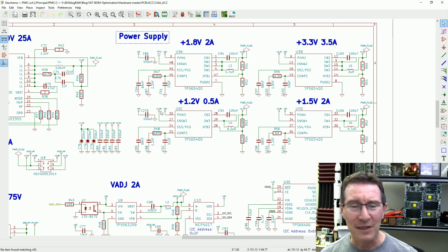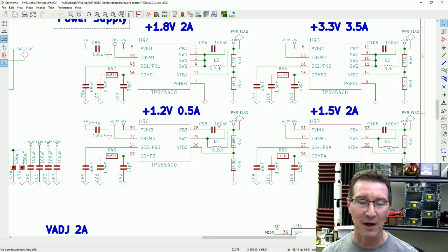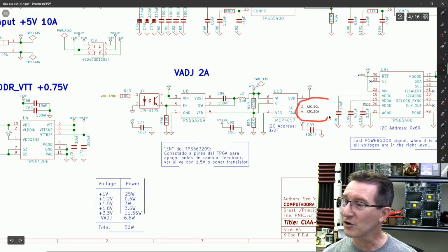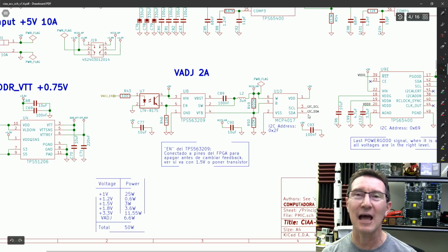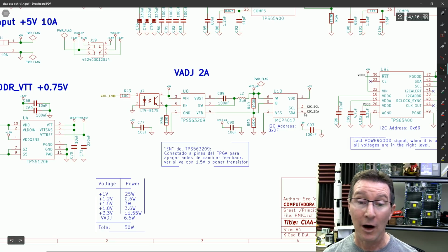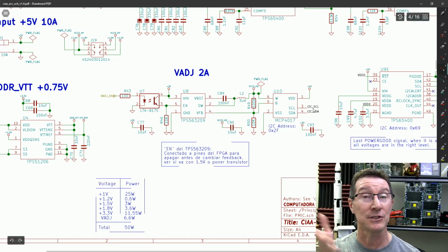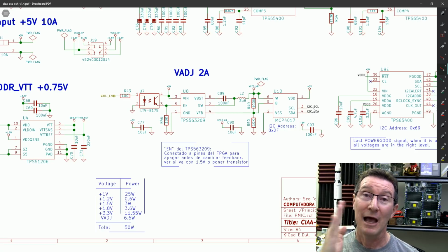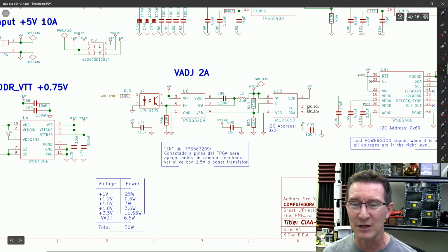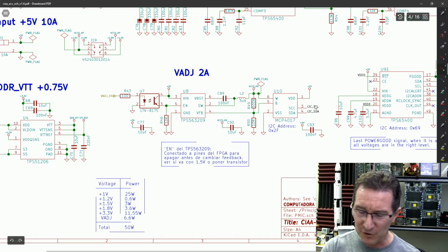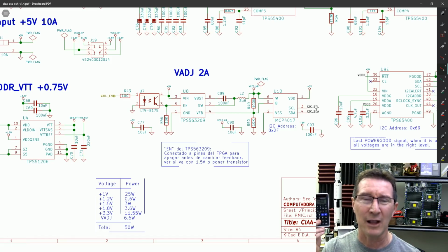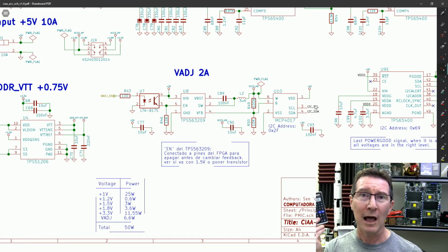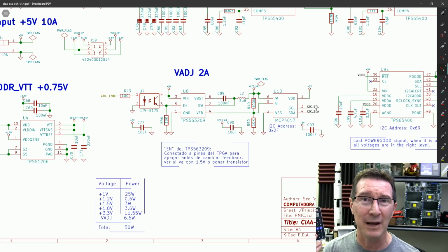But anyway, there are so many more ways that you can optimize values in designs like this. For example, we've got an I2C line here that's going to have certain pull-ups. The lower the value of the pull-up on your I2C line, the higher the slew rate, because it's an open collector output, and the faster the slew rate, the more speed you can get out of your I2C bus. So if your calculator popped out a value like 1.8K for your pull-up, and you don't use 1.8K anywhere else, why not use a 1.5K?